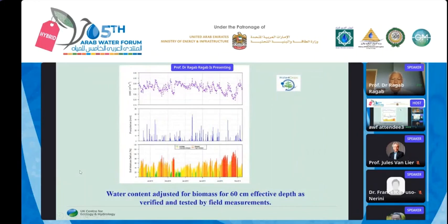And we have been looking at the possible use of Cosmos in terms of irrigation. You can see here we can get the soil moisture over time as a time series from 30 minutes onwards. And also here you can see how the soil moisture responds very well to rainfall events. So it is a very sensitive instrument. We converted the soil moisture to soil moisture deficit, and we actually give the deficit a color code. If it's green, we don't need to irrigate. If it's amber, it is a slightly stressed soil. And if it's red, it means the crop is really stressed and you need to irrigate.